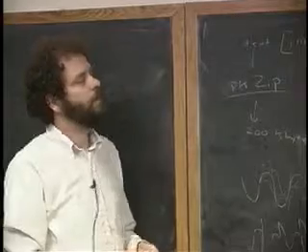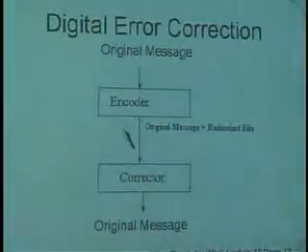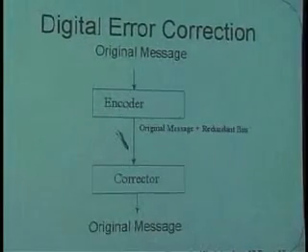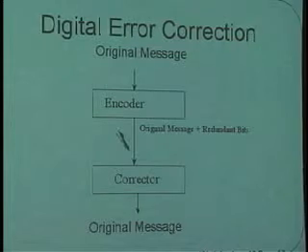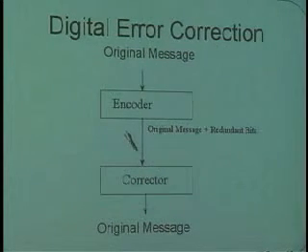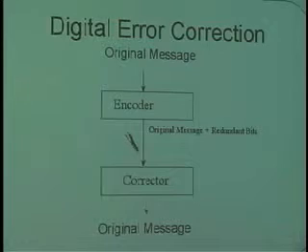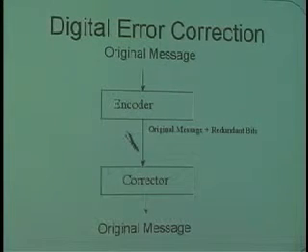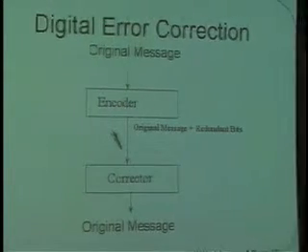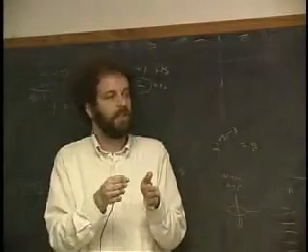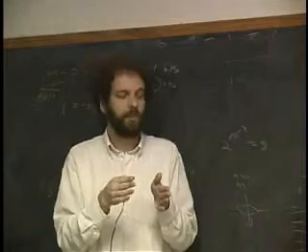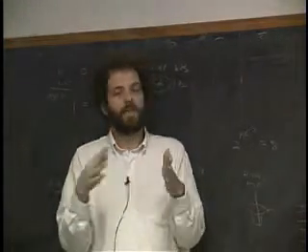But it turns out there is a good reason that you and I do not speak as efficiently as we can. And here's the reason. If I put in redundancy to begin with in my language, then you can tolerate a little bit of noise. And this is different than the analog noise I was talking about in the last lecture, where a very simple receiver could just say anything that's higher than the input threshold or lower than the input threshold is going to be either a 0 or a 1. That's one form of tolerating noise.